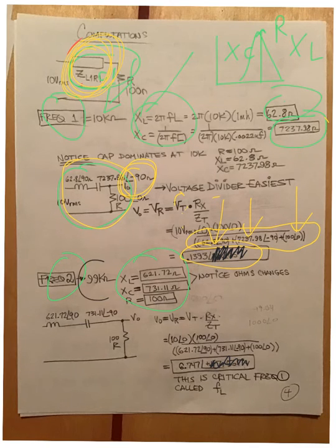Moving up in frequency to 99K, now we get to one of the 3 dB points, and you see in this location right here that the inductor and the capacitor are starting to change. The capacitor is starting to shrink in value.